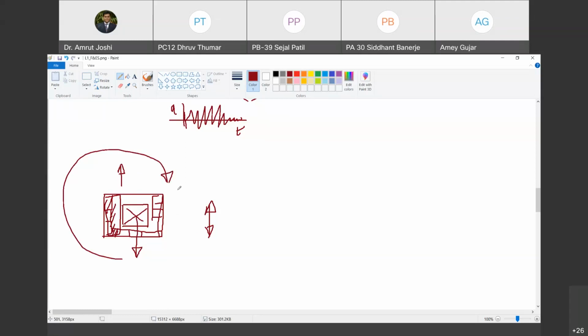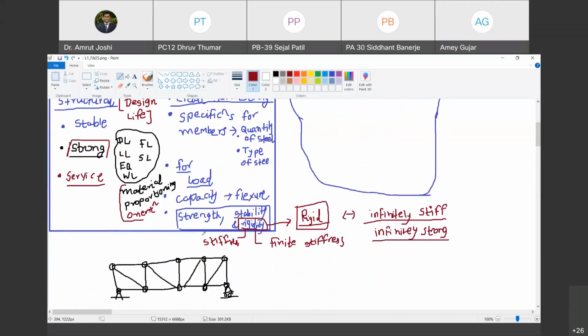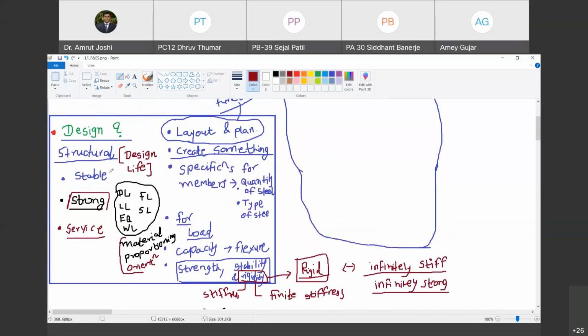Yes, sir. So even though the earthquake occurs in this direction, you will see the building twisting in plan as a response to the earthquake. This is because of the difference between the locations of the center of mass and the center of stiffness of the building. So how you proportion stiffness is another example. In all these examples, I have highlighted the importance of providing a particular stiffness in a particular fashion to a building. So what is the task at the disposal of a designer?